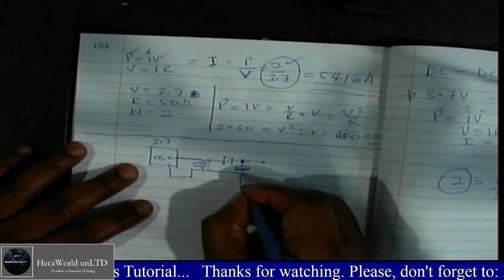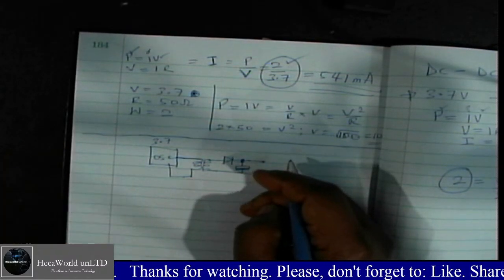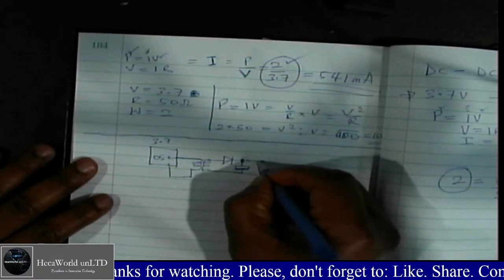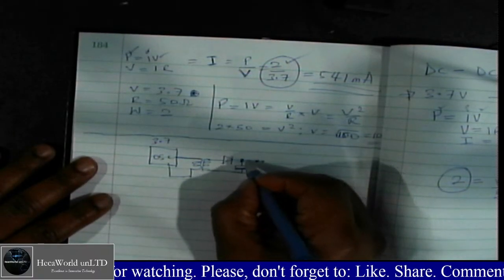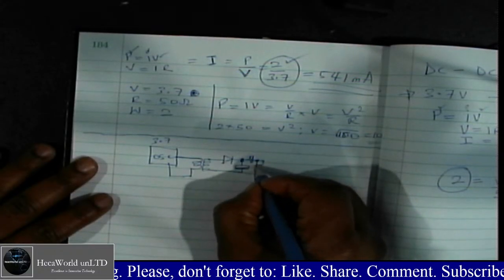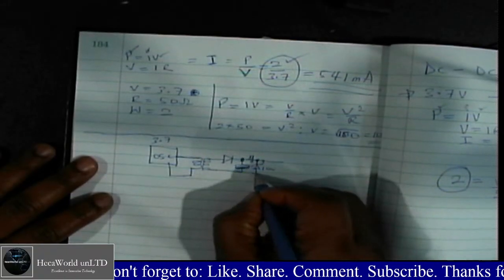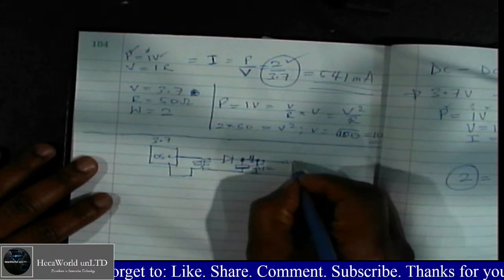And then, since I need it to be 10 volts, I would have to include a Zener diode somewhere. So maybe I have a resistor here, then a Zener diode here, and this Zener diode will be a 10 volts Zener, and then I have my 10 volts here.